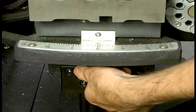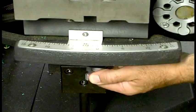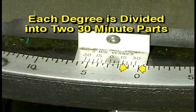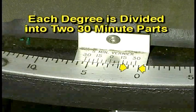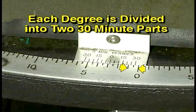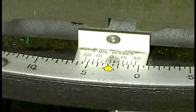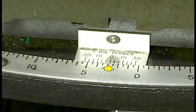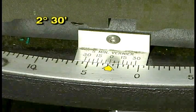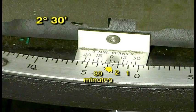Once the helix or pitch angle has been found in the reference guide, loosen the clamp and adjust the table to the specified angle. Notice that each degree on the scale is divided into 2 spaces. Since there are 60 minutes in each degree, each space represents 30 minutes. The 0 line on the vernier scale points to the number of whole degrees. Here, the 0 line is located past the 2 degree and 30 minute space. Therefore, the degree scale reads 2 degrees, 30 minutes.